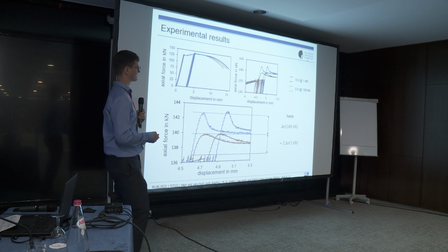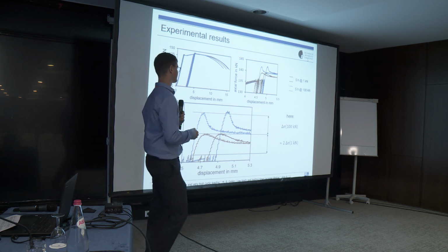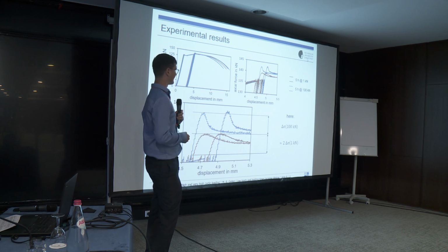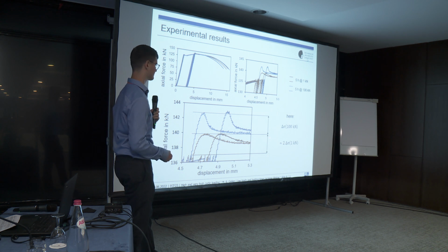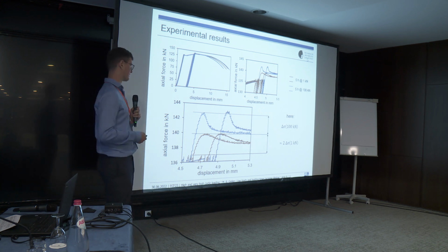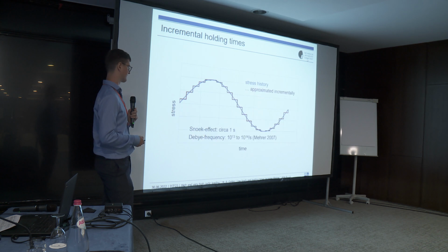And as we see here, we did see another yield point phenomenon. We would expect, if there was no strain aging, these lines to continue like the lines that went there before. And here we have it in a bigger view. And we see that the stress increase of the specimens that were held at 100 kilonewton is double the stress increase of the specimens that were held at 1 kilonewton. And therefore, we have experimental proof that static stresses do increase strain aging.